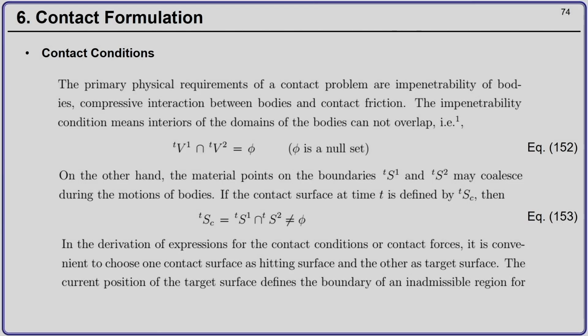Once we have completed our thermal formulation, our final job is to do the contact formulation. Now, all the derivation that we have done till now is for a two body contact problem, and at the contact surface we know neither the displacements nor the forces. So, we have more unknowns than the number of equations. So, we have to generate some extra set of equations, and these will be generated using the contact formulation.